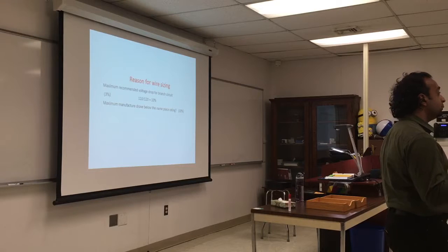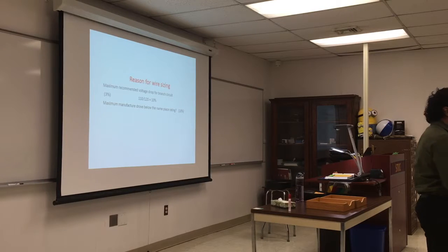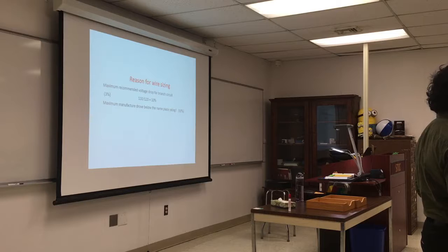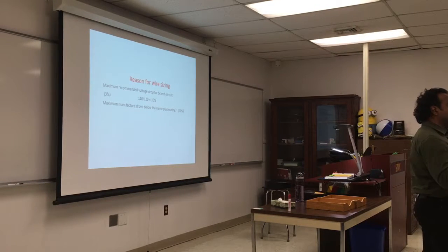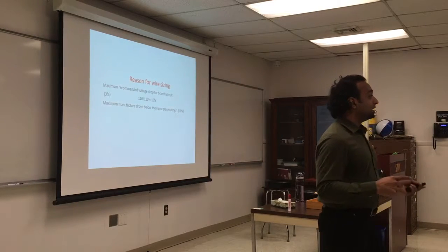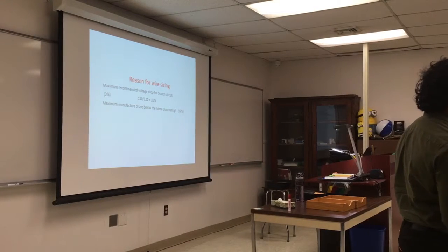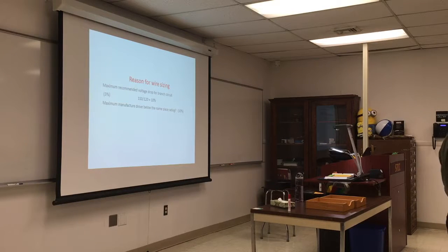How long is it? When you try to install new equipment, especially a condenser that's outside, and you have to run a long wire, within 100 feet it's okay, it has been calculated. Probably in the installation they will tell you, within 100 feet or 100 yards, whatever limit it is, it's okay, you don't have to change the wiring. What if it's longer than that? Probably you have to consult the manufacturer and see what wire you should change to.